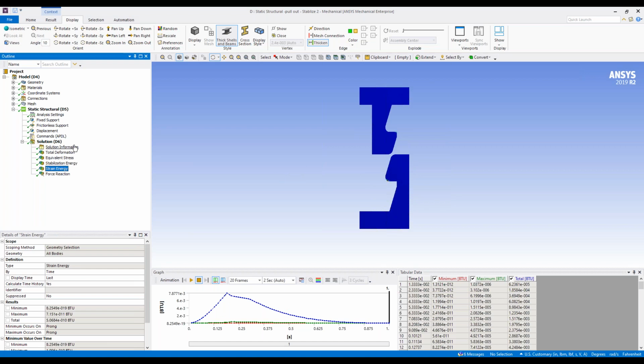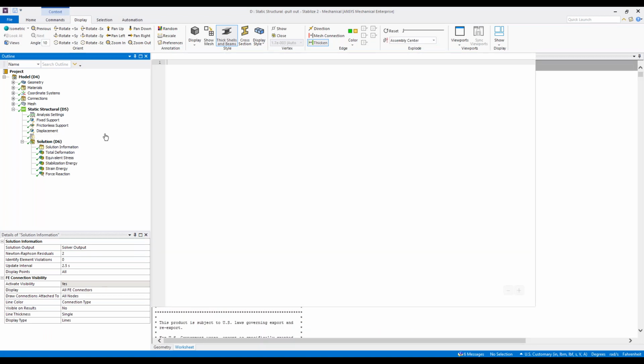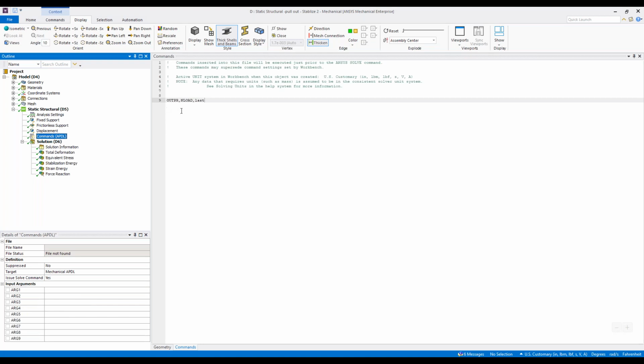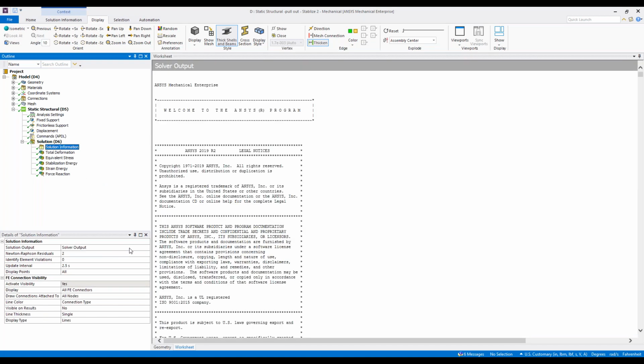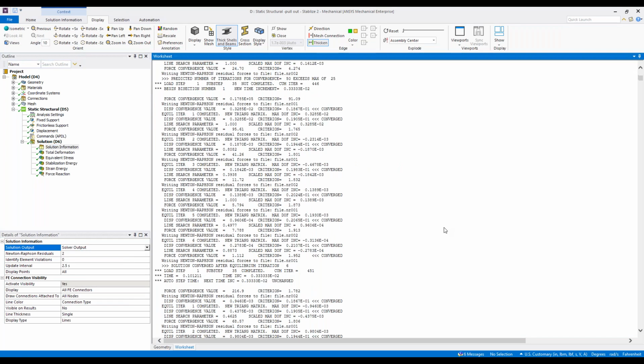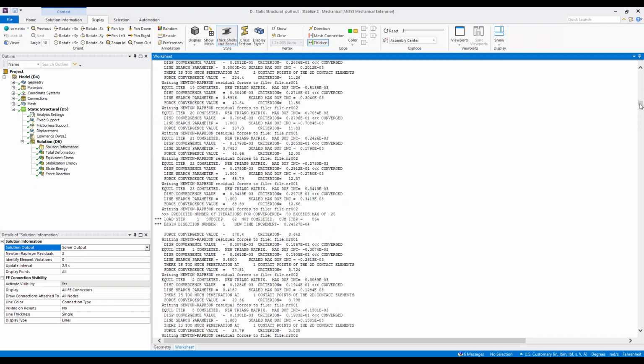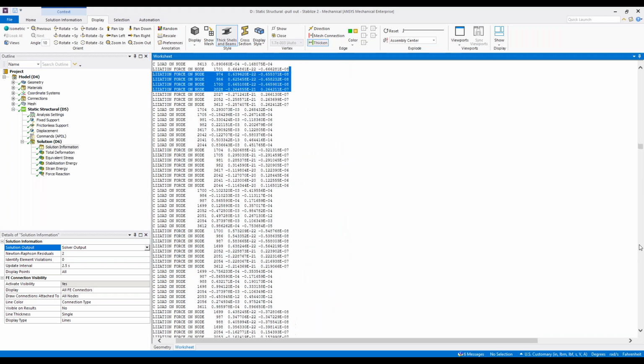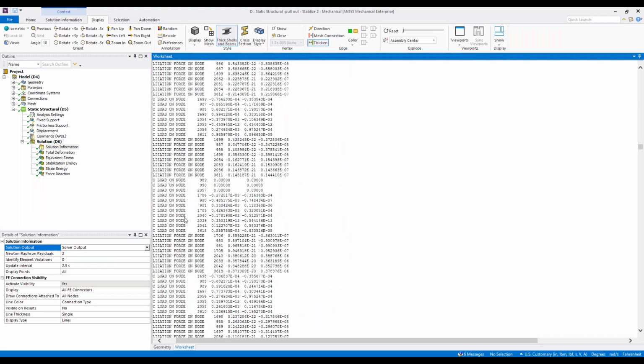Okay, and then you can also look again, as I said earlier, at the output forces, which we're asking for here. These ought to be small. Now you will wonder where these forces are coming from. Well, this is the output file. This is too big, I'm sorry. Come on, system. See, this is the forces listed for you. You basically see the static force on the node along with the stabilization force on the same node. So if I look at node 17, for example, you have e to the minus 21, e to the minus 7. Compare that to e to the minus 3, e to the minus 4. Certainly, the stabilization forces are small, and hence the solution numerically is acceptable.